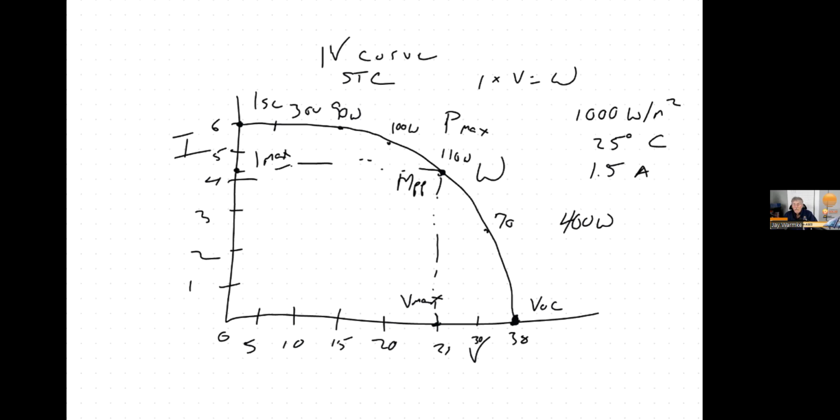So this is the upper voltage that we're going to use when we're trying to design our system to live within certain voltage limits. And the amps, we're going to use that number when we start sizing the wire so we don't overload our wire and cause it to catch on fire. So these are two design criteria numbers.